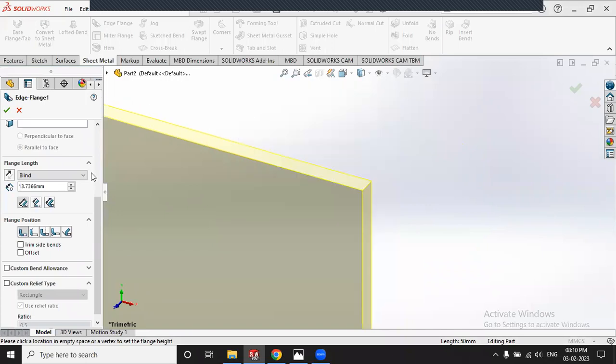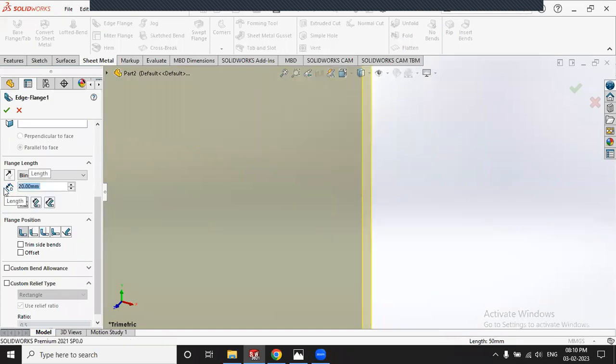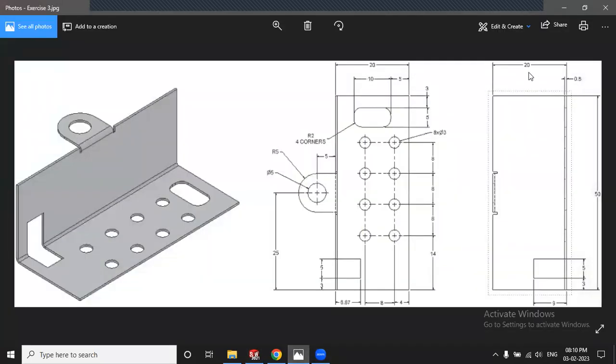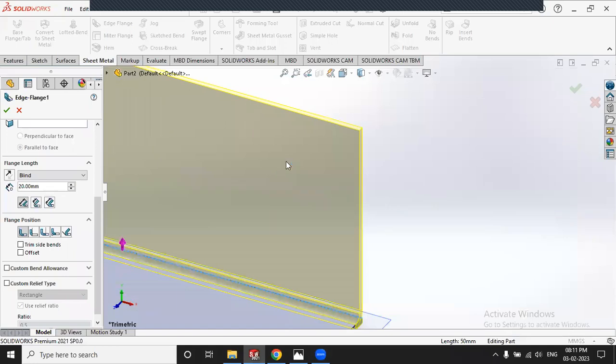Okay. So how much do we require? We require 20, so we will assign a 20 mm height. How do we know it's 20 mm? If I go to sketch again, in side view you will get the height from bottom to top. It means from the base's bottom side to the top side is 20 mm, right? Okay, so you will get this option here.